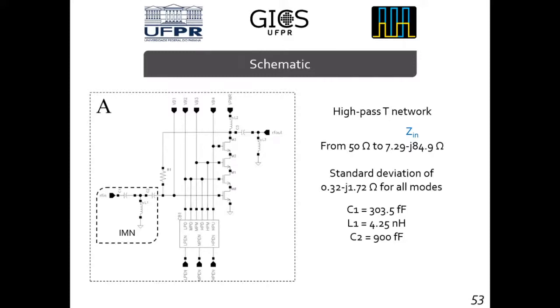Yeah, I understand what you're saying, Professor, but something that happens in the circuit is that VB1 is always fixed in 0.52 volts. So we'll actually have the drop between the drain and the gate of M3 and M1, but as the circuit always has the same fixed VB1, I designed the circuit to work around the situation. So maybe it would be a better idea to add the C1 so I could not face this type of issue.